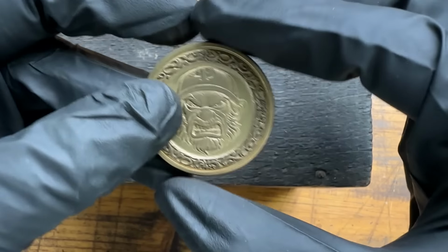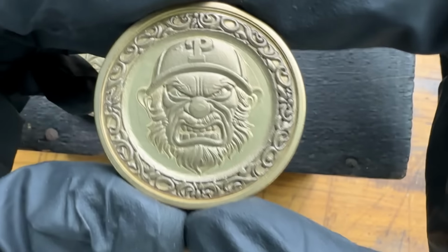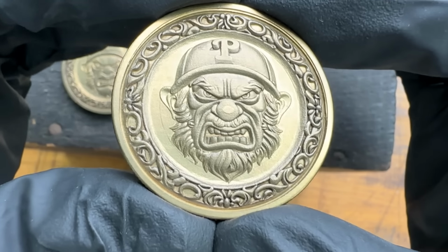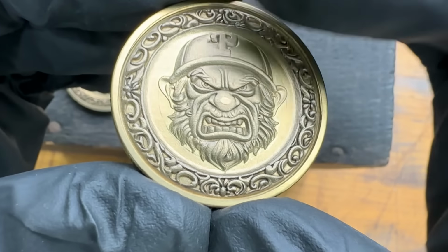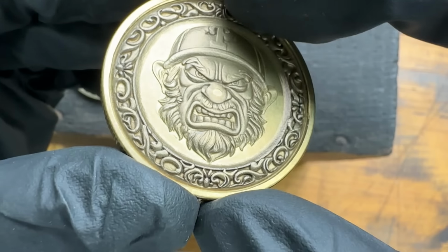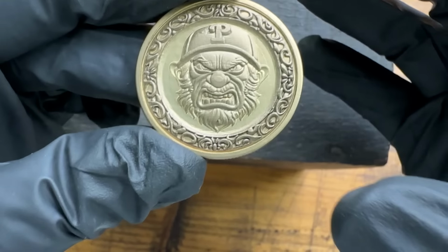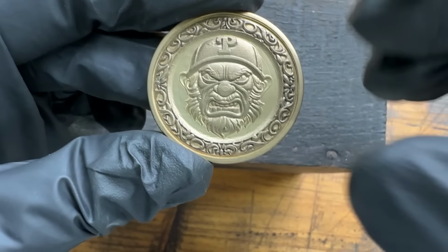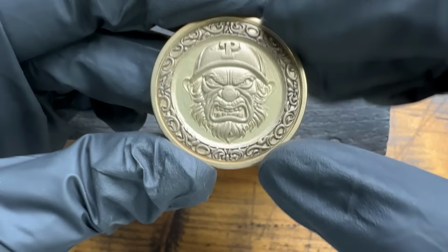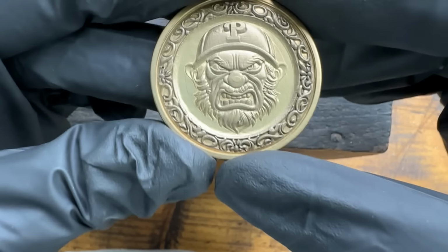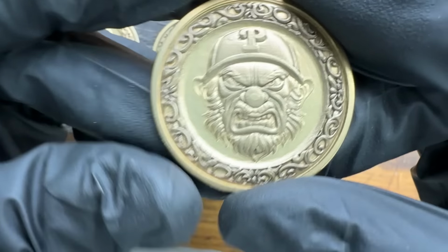Now, for the 200 kilohertz example, this is the one I was most interested to see because I've never done this before. And look at that background. Look how smooth that is. It's almost like a perfect smooth dish look. And that's because at the higher frequency, the laser spent more time in contact with our brass, therefore it smoothed it out. And even as far as going across the face, I got a lot more depth than I was expecting.